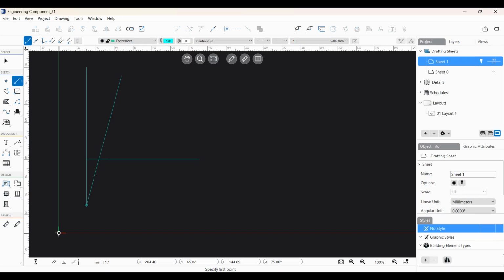Let's see now how applying geometric rules to the drafting procedure is a fundamental step when you need precision, accuracy, and consistency of the design elements. The drawing constraint functions allow you to quickly draw items with some conditions, such as parallelism, defined angle, or intersections. The input fields on the input bar allow you to enter the coordinates of drawing points and the geometric dimensions of the objects, like length and angle.